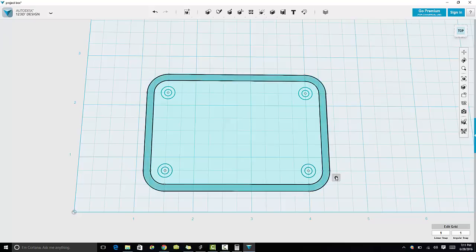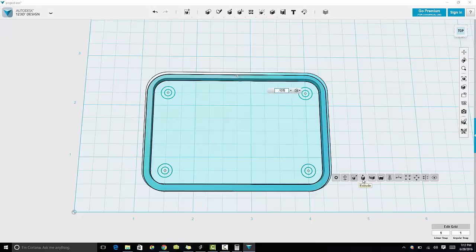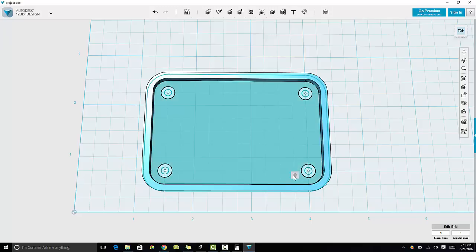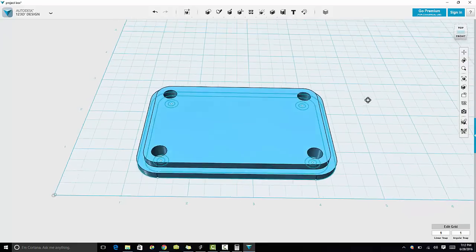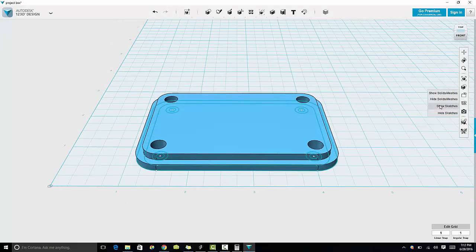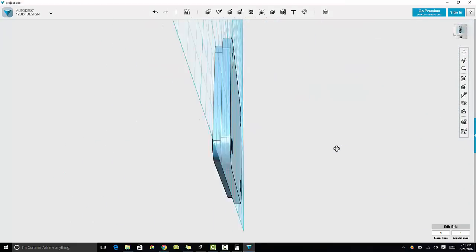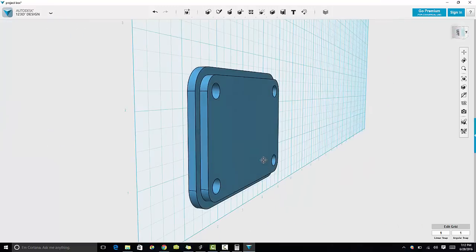All we've got to do is click in here, click the gear, click the extrude button, and say 0.125, 1/8 inch. No surprises there. I feel like we all kind of got the picture at this point. And we will extrude again 0.25 inches, the inner part. So just like that, we have a nice little lid here.